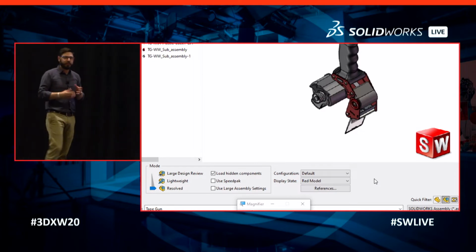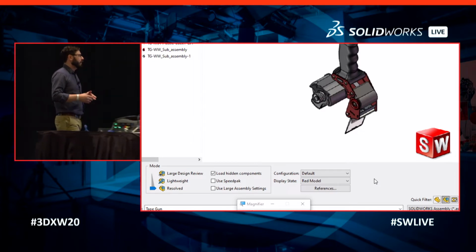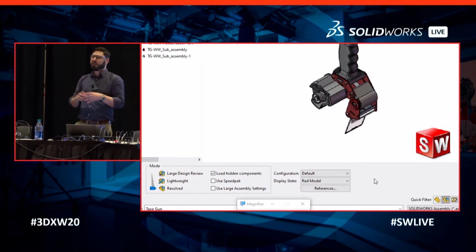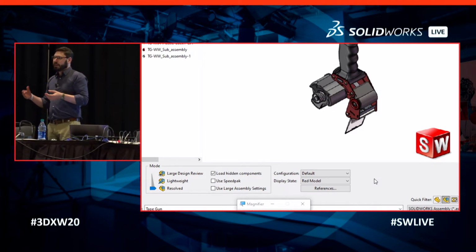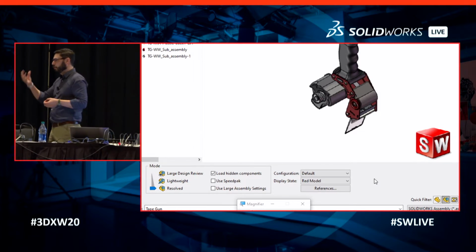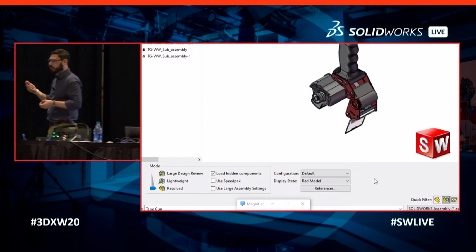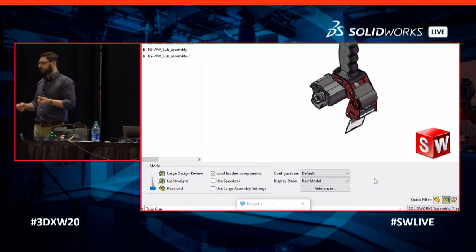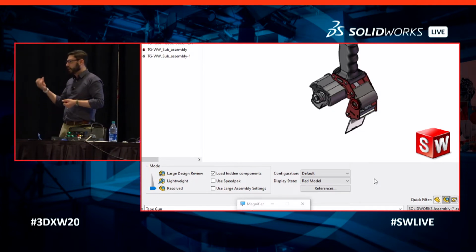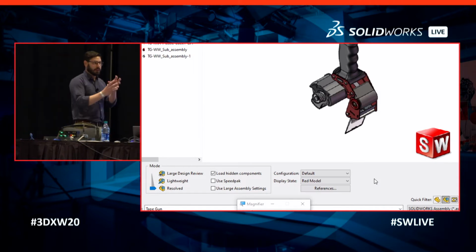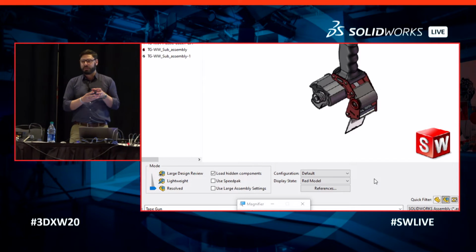Let's think about this from a sheer mathematical standpoint. When you open up an assembly, it's opening all those components that are shown. They're all loading into your RAM and your graphics card. If you've got a really big assembly, you're opening a lot of components, and you're putting a real heavy strain on your computer. Let's say I only need to work on a little tiny subset model.